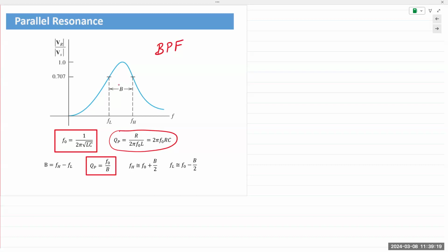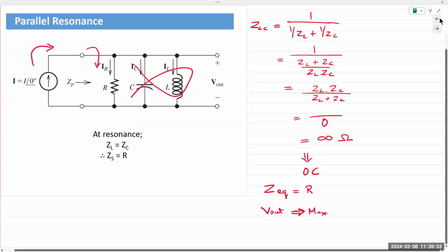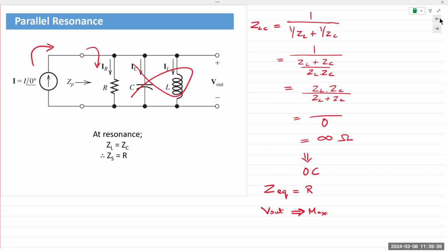All right, 10-second pause. Let me know if you have any questions. Professor, for lab, we had the parallel circuit with the 10K and the 50K. 10K was in series, where that white node is at the top, and the 50K was where that R is. So that means the resistance that you use to calculate your half frequencies would be them added together in series? In parallel. In parallel, because the source would be shorted out, and so use them as in parallel. Okay, thank you.